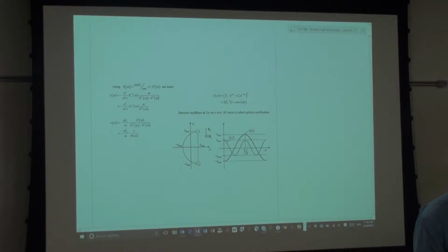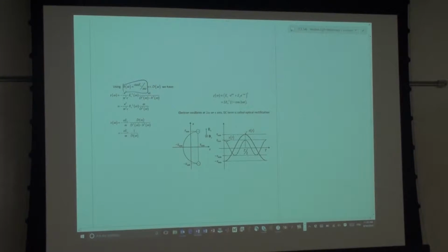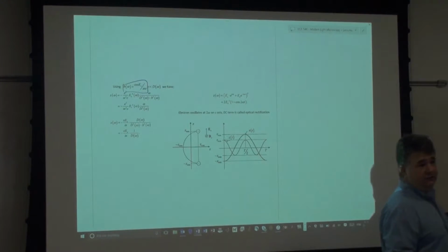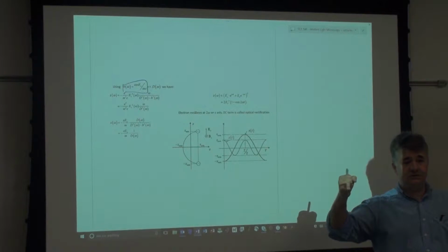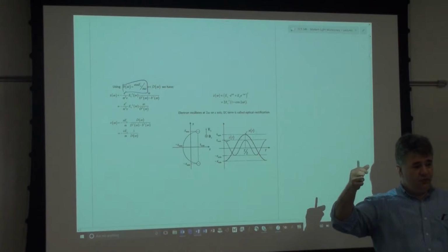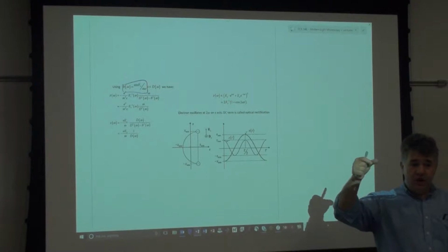Okay, so usually with all nonlinear problems, we try to linearize them first in a way. The intuitive picture is like this. When you stretch that spring and you change its constant, that's a nonlinear problem. But if you now operate around the stretched spring, around that new equilibrium position, and apply new forces, you can assume it's linear around that point.